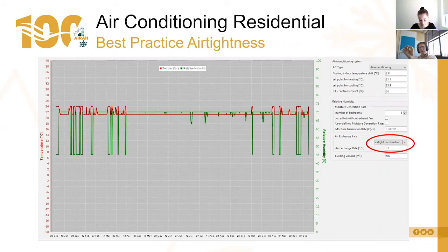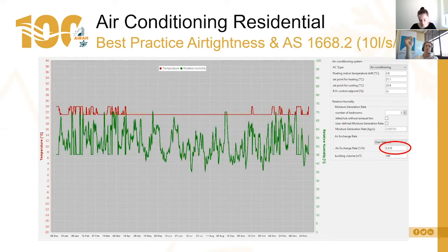The other thing you can look at is select the air tightness level. So you can have an airtight construction or a standard construction. And if I have an airtight construction, it drives up the indoor humidity. Then if I start putting a controlled ventilation rate through, what this allows all the mechanical engineers out there to do is say, if I have a controlled mechanical ventilation strategy in, say, this apartment, you're much less likely to get mold and moisture build up in the building envelope of this apartment block. And the reason for that is because you reduce the indoor humidity in the building, and then the calculation can be made under 2 different scenarios and compared for what the risk of mold growth is.